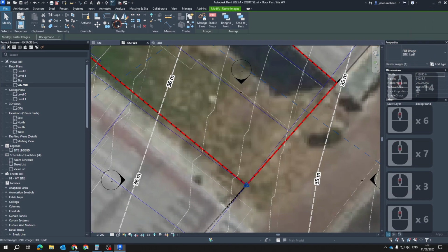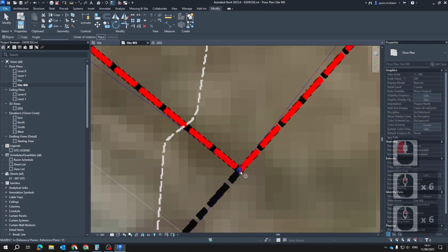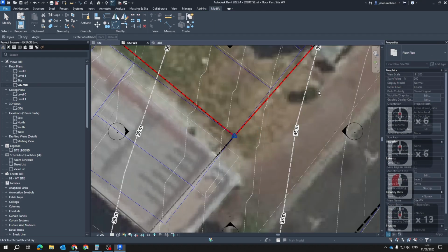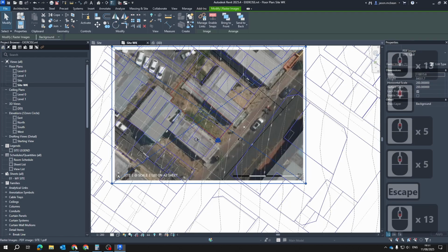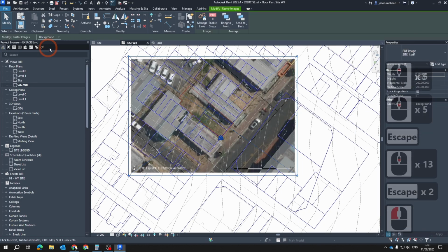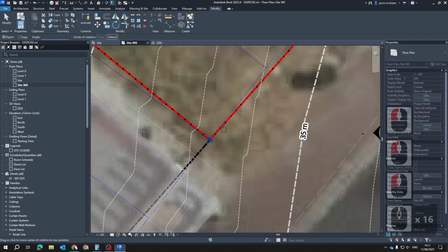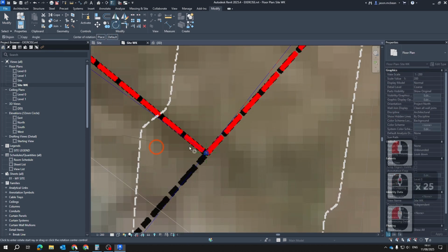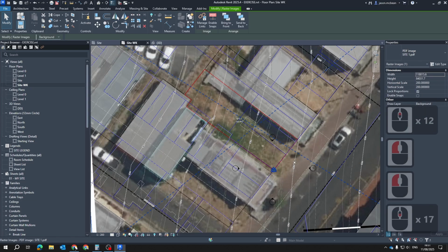And I've noticed it's slightly off axis, so I'm going to rotate it as well. So I'm going to say place, rotate, and I'm going to rotate this image. So select your image, the image selected, rotate. You're going to say place. You want to place an origin from which to rotate. I'm going to use my project origin, and I'm going to select a point over here, and I'm going to rotate it back to. Okay, so that's the first step I had to do.